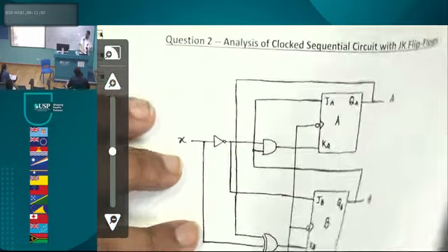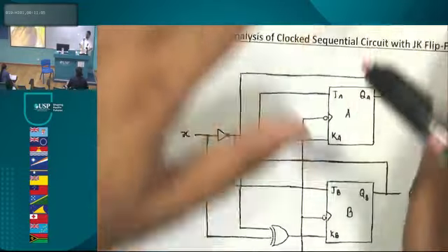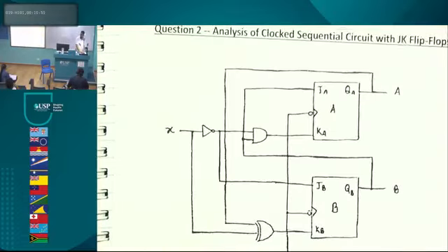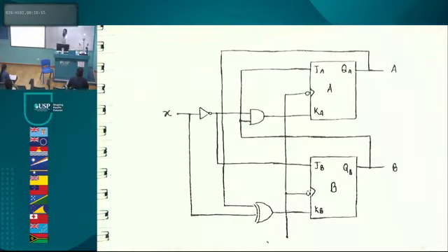Guys, let me ask you. So obviously, this is some type of sequence generator, right? As you go through, it will generate some sequence. Look at this one. So how do we display? If you want to use a 7-segment display, you guys know what a 7-segment display is from week 7 or week 8, right? If you want to display this on a 7-segment display, how do we display this, guys? You're going to connect this. This is output 1, output 2. You see, QA is A, output B. You'll connect this to the 7-segment display and it'll show 0, 1.